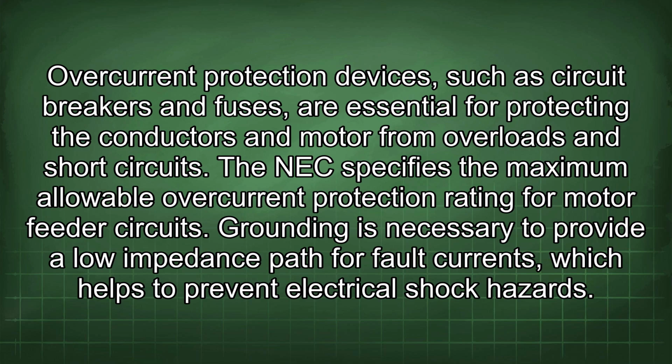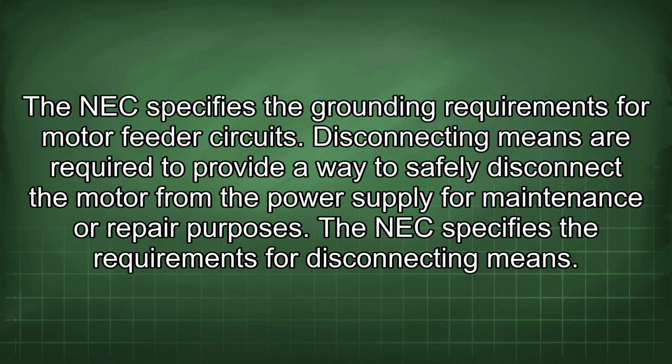Grounding is necessary to provide a low impedance path for fault currents, which helps to prevent electrical shock hazards. The NEC specifies the grounding requirements for motor feeder circuits. Disconnecting means are required to provide a way to safely disconnect the motor from the power supply for maintenance or repair purposes. The NEC specifies the requirements for disconnecting means.